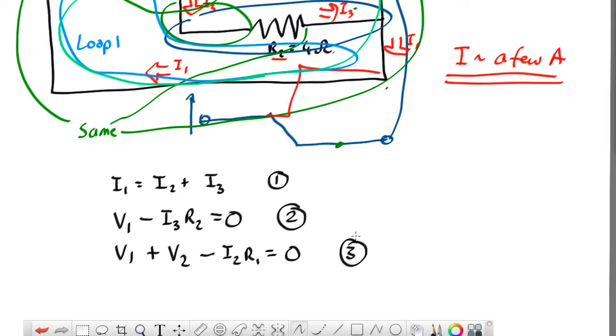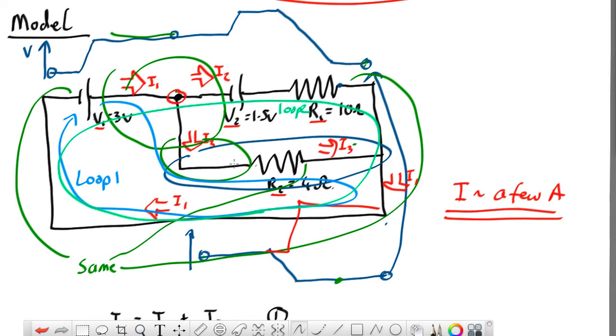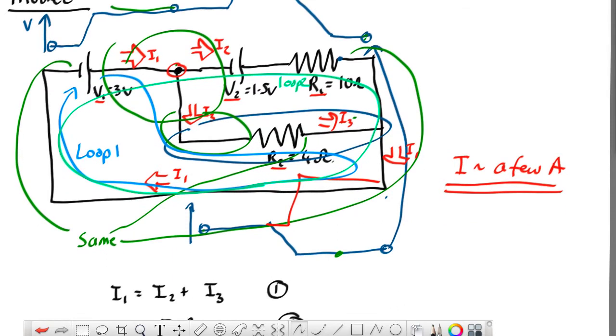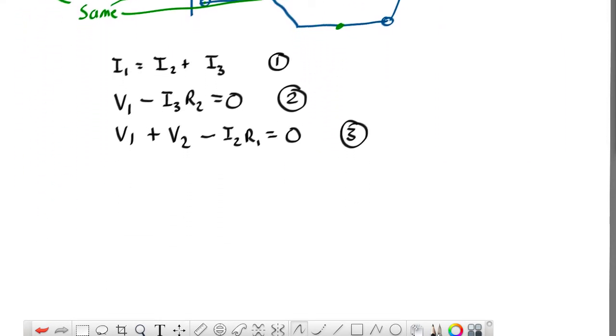So we've got 3 things we're trying to work out, the 3 currents, and we've got 3 equations, so 3 equations, 3 unknowns, thus we can solve. We could, if we like, do our third loop, just go around here. But you'll find that that's just going to tell you things we already know. We've already got at least one loop that goes through every component, so we've got enough loops to solve the problem. Okay, so now it just becomes maths as we solve this. Notice that I've done everything in the form of algebra, using symbols. I've not substituted numbers in. We'll substitute numbers at the end. That's always good strategy because it gives you more ways to check your answers.